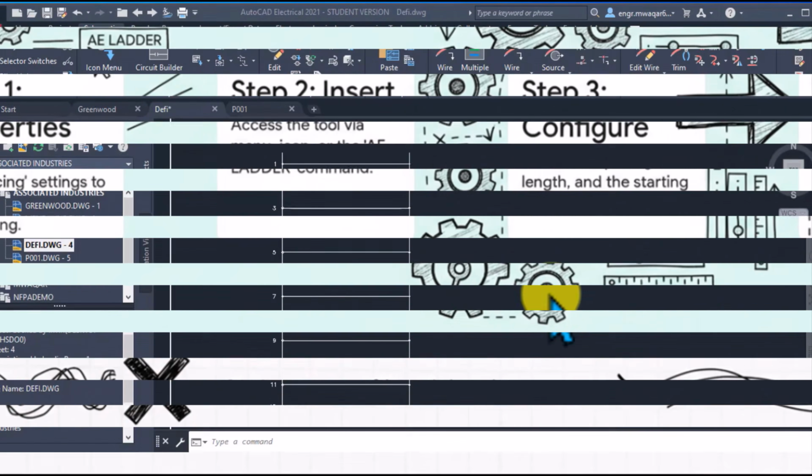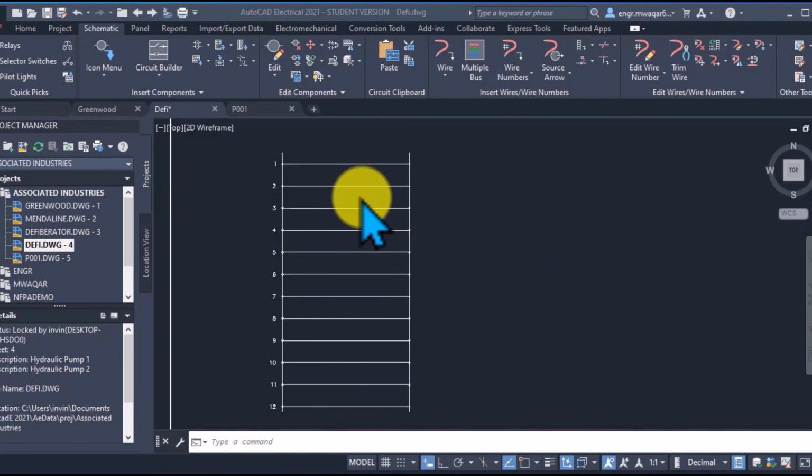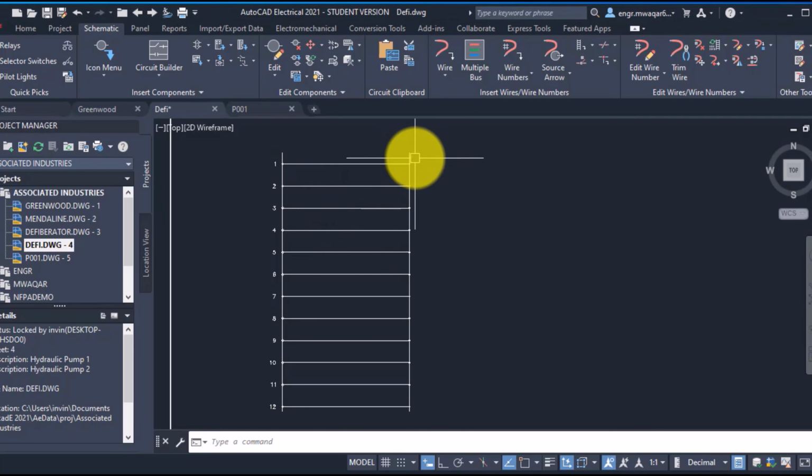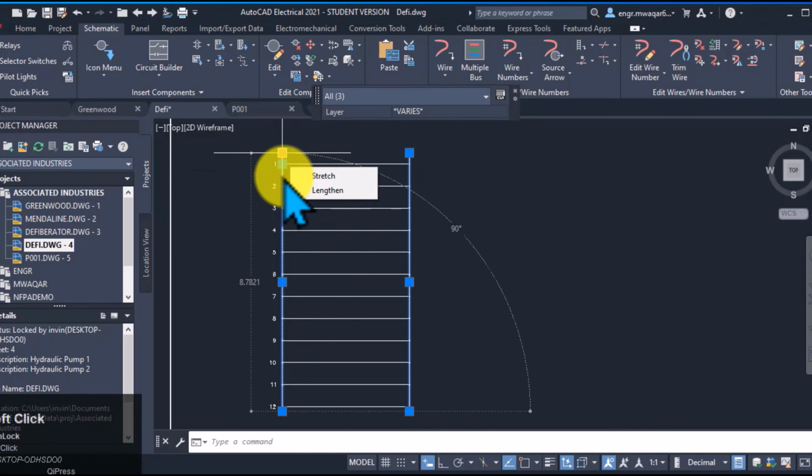There are so many parameters. You've got width, spacing, length. And those are the physical geometry settings. Width is obviously the physical distance on the page between your two bus rails. Spacing is the vertical distance between each rung. But the setting that really caught my eye in the research, and the one Suntech highlighted, was reference numbers. The source mentions you have a choice, basically, between numbers only and numbers and ruling.